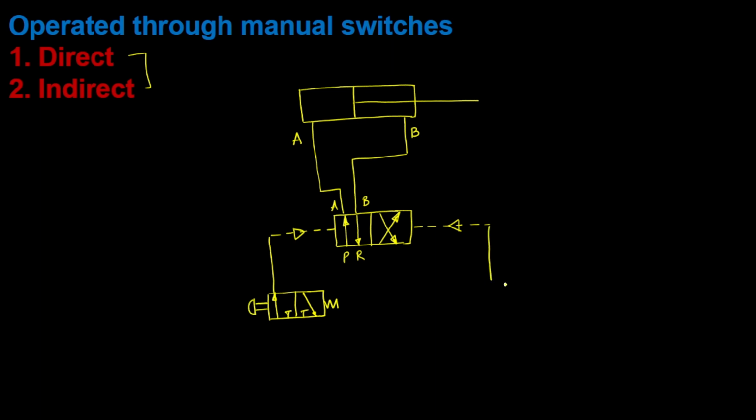and here also the 3x2 valve is getting utilized. It is a simple on off switch. Okay, so this is a 3x2 valve. Now here this is pressure, return and A, and let us say here B, pressure and return. So now what will happen? Let us say this is valve number V1, this is V2, and this is valve number 3.